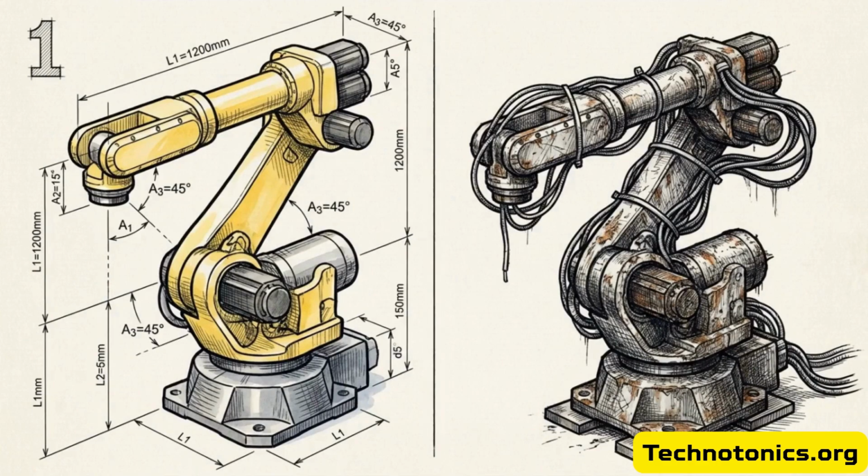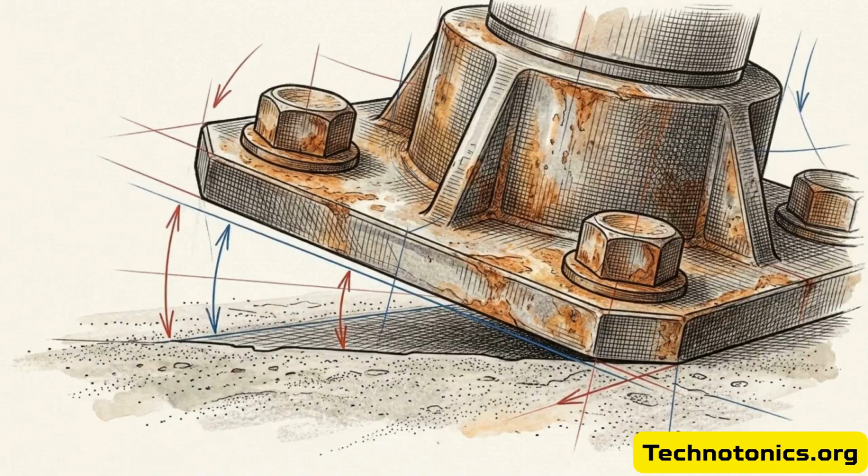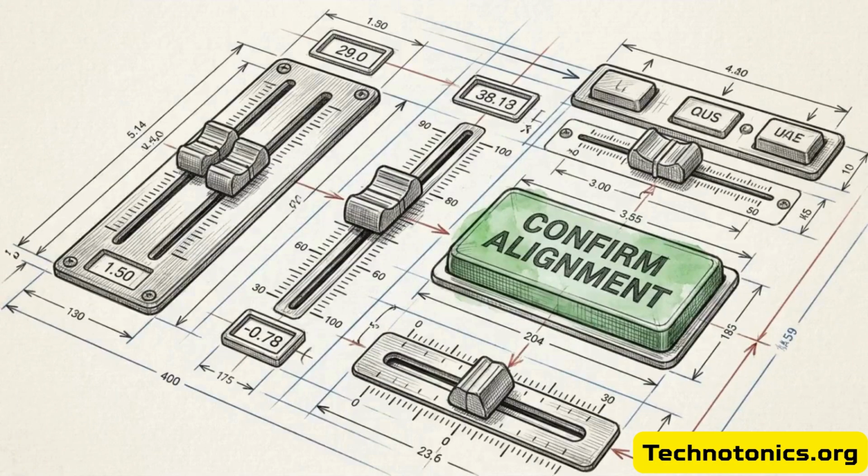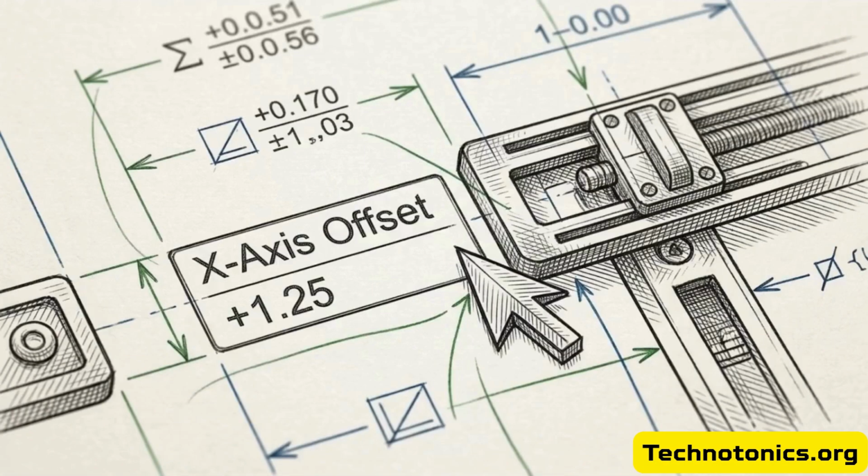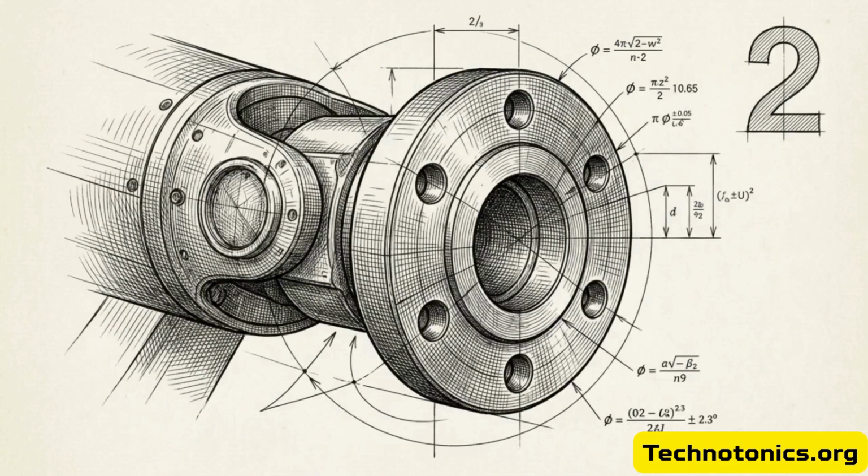Step 1 is robot calibration. A common trap is assuming the default digital model in the software perfectly mirrors your setup on the factory floor. Physical wear, mounting variations, and slight factory tolerances mean they rarely match out of the box. To fix this, open the RoboDK calibration module. Work through the prompts, using the sliders to align the digital model exactly with your physical robot's known configuration.